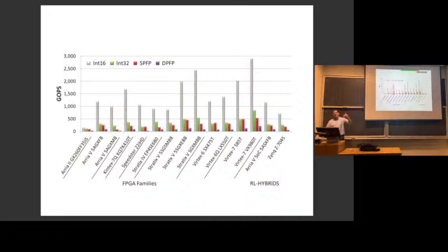So it's a bigger difference than it was for the processors because we're basically building these multipliers out of DSP blocks and logic elements, and it's more like a square than a linear change when you go to a bigger multiplier. The other thing is we lose some more when we go to floating point. Most of these have lower results for floating point, and it's because floating point takes some additional logic.